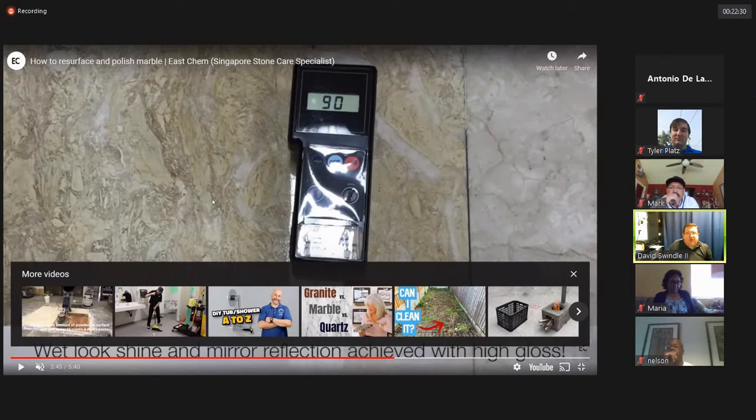So it's thicker than a piece of ceramic tile or porcelain tile, generally speaking thick enough. And in the polishing process, you're not taking off much material as it's honed and polished. On concrete, you can remove up to a 1/16 of material real quickly in the grinding process. Marble, you'll never be able to remove that much, or granite. And granite's even harder than marble.